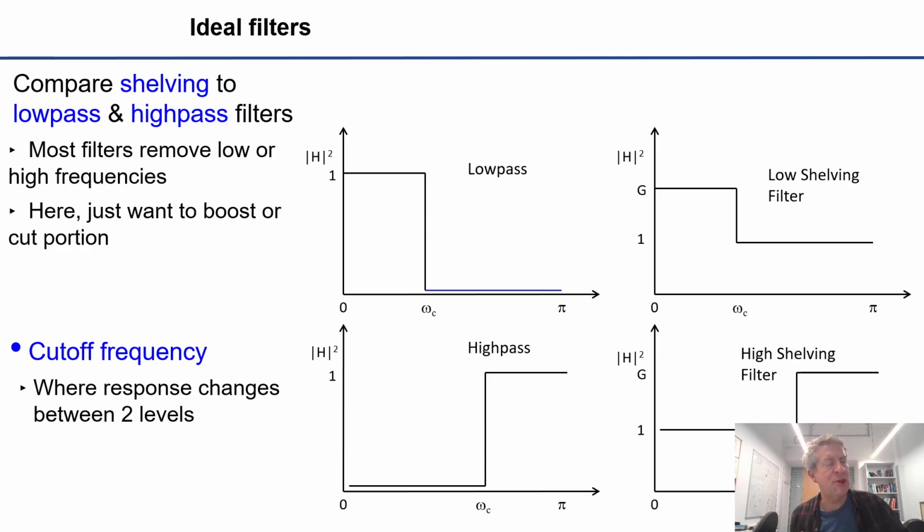So we talked about general properties of filters. We haven't gone through the main filters that are used with audio. And if you've studied digital signal processing, you will recognize many of them, but not necessarily all of them. There are some filters that just aren't typically covered in a standard DSP textbook, but are still quite important with audio. First, we have low-pass filters. Those are the ones that try to keep the low-frequency content, but remove all of the high-frequency content.